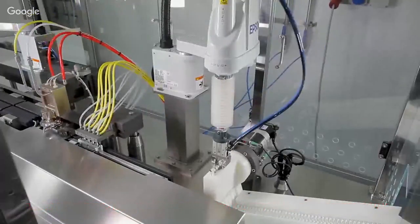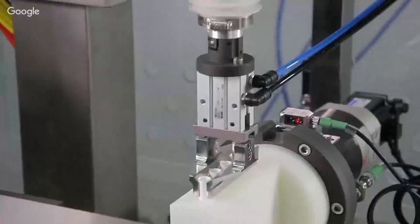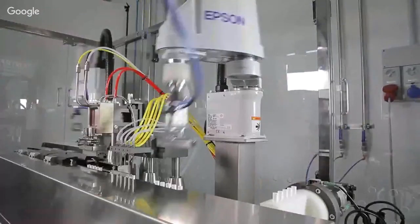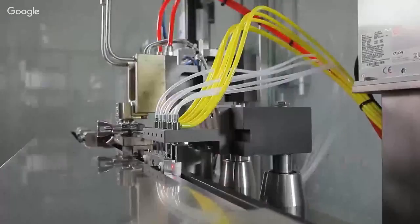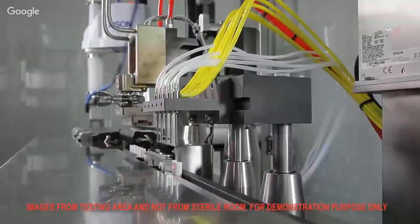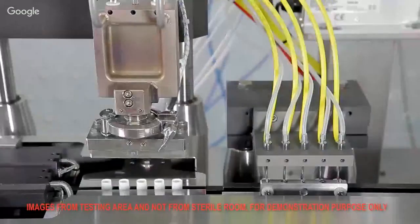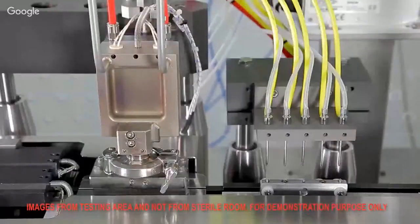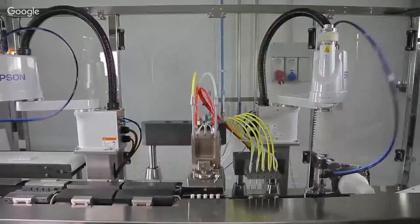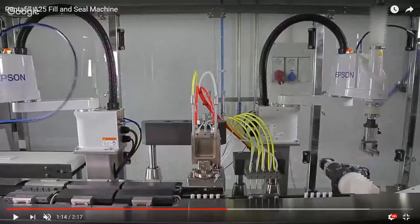As you can see, the pick and place is picking the strips of 5 vials and placing them into the stainless steel guide that then moves the strips to the next station. We equip the machine with a code reader that obviously reads the presence of the vials. If for any reason the vial is not loaded, then the machine does not fill.